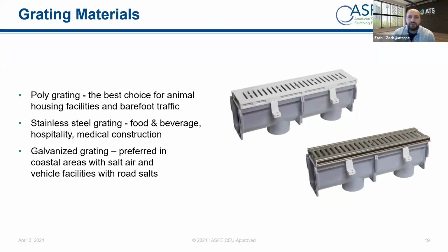I don't believe there's any difference to the ADA aspect of it. I don't know that there are specific ADA grates, but I would imagine there are quite a few that are less than that 1/2 inch. If we're looking at this grate here, the stainless steel one, that could just as easily be done in galvanized, and that's not a very wide slot there, so that would likely still meet the ADA.